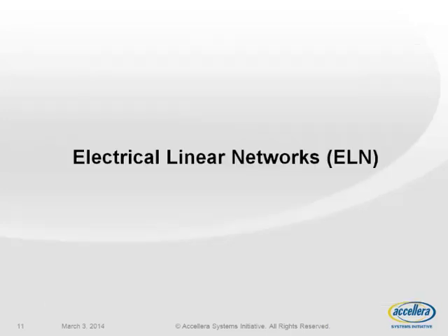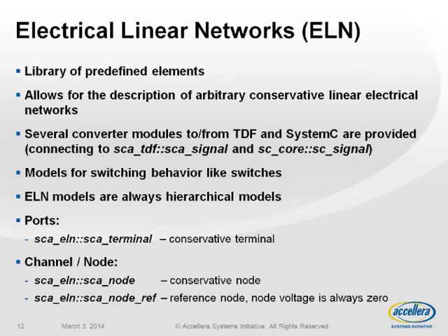So a short talk about ELN. This is the third model of computation available in SystemC AMS. It is also composed of predefined elements, and this is the only model of computation of SystemC AMS that is able to keep the Kirchhoff laws in order, that can model a conservative linear behavior.